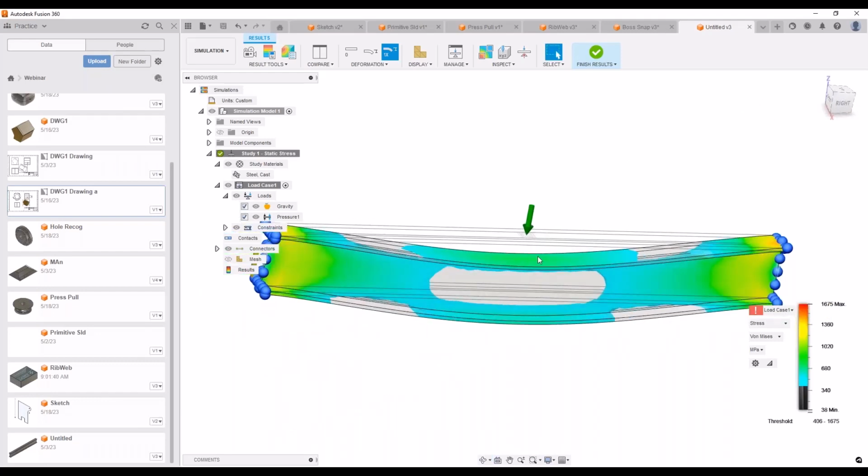and you can strengthen, fasten, maybe add your gussets and your ribs to strengthen your part under these circumstances. This allows for a lot of flexibility in the design that you have. So use the stress tool to actually change your design. You can even strengthen or weaken certain areas.